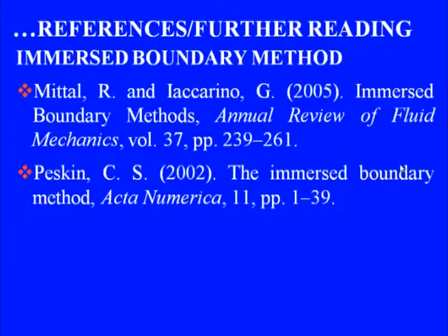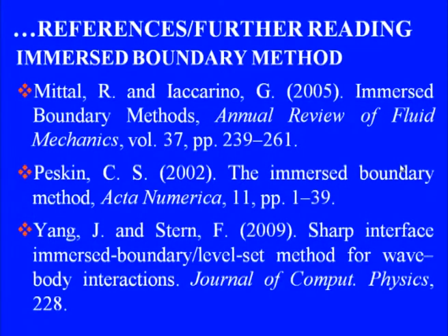For immersed boundary method, there are many research papers available. You can look at the review paper of Mittal and Iaccarino published in 2005 in Annual Review of Fluid Mechanics, or you can look at the classic paper of Peskin in 2002 on immersed boundary method published in Acta Numerica, or recent ones by Yang and Stern published in the Journal of Computational Physics on sharp interface immersed boundary level set method for wave body interactions. And this particular methodology helps us to get a near exact representation of a complex or curved interface. That's why it's called sharp interface immersed boundary level set method.